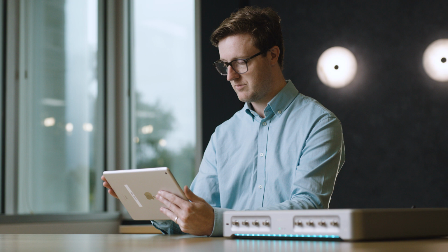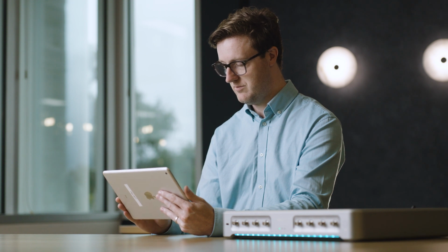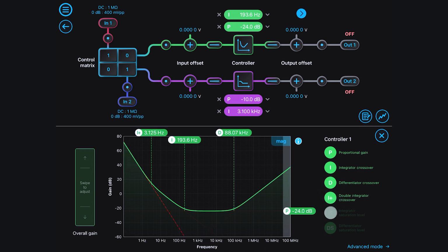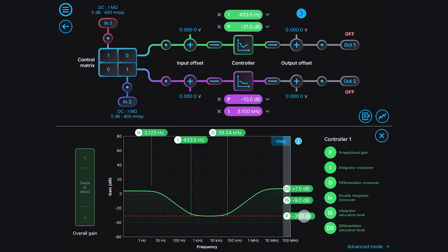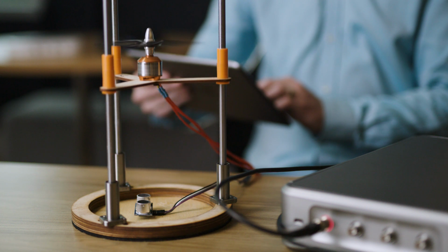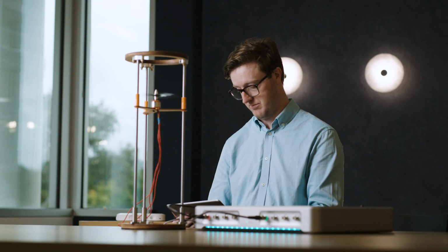its time integral. The Moku Pro PID controller has some extra features as well, including a second integrator for extra low-frequency gain, and configurable integral and derivative saturation points to help achieve the best outcomes in noisy or high-disturbance environments. PID controllers are really the workhorse of real-time control applications. You can use them to control lasers, motors, servos, piezoelectronics, and much more besides.